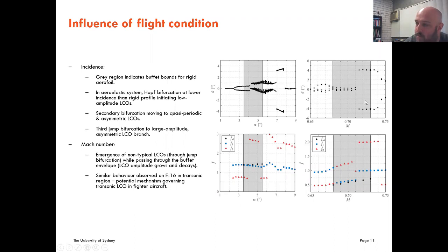And this is potentially starting to give us an understanding that the aircraft is actually experiencing some form of buffet behavior that gets coupled with the structure, or with having a tip mass, because the change in that tip mass will alter quite dramatically the behavior of the system.